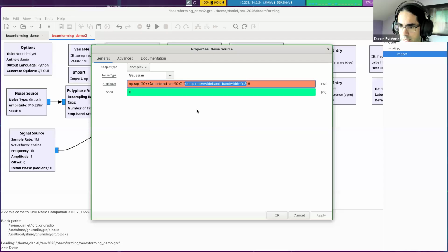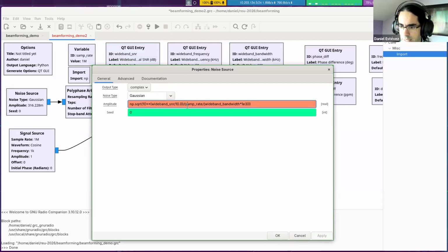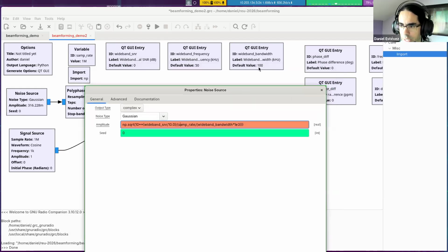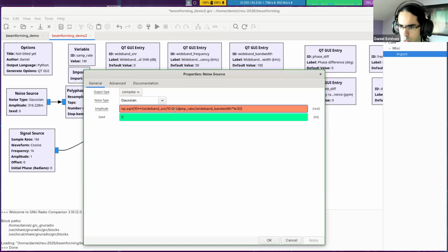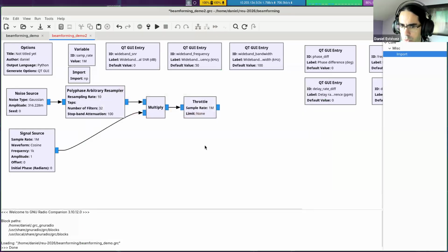So what I'm saying is I should divide this quantity by 10 because my signal to noise ratio is defined as the power of this noise source divided by the power of 1/10 of my noise floor, because it's my noise floor only in this 100 kilohertz bandwidth. So that's how this works out to be. We could rearrange this also, and this thing which is twice on the denominator, we could put it multiplying on top. But that's what we want.